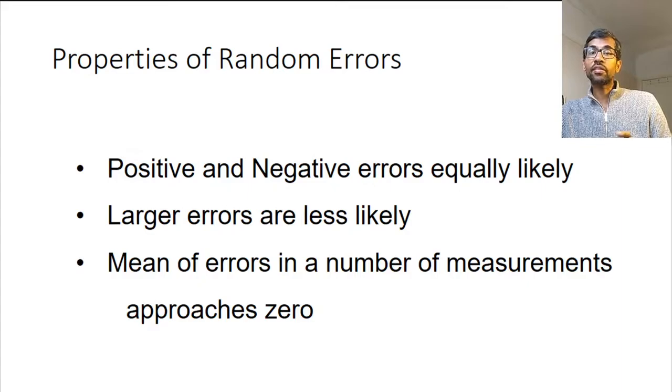Another way to figure out systematic error would be to get a validated instrument from somewhere, an instrument that has much less errors or that is more standard, and measure the output of your sensor or your instrument compared to that standard instrument. That could also reveal systematic errors. In general, systematic errors are much more difficult to figure out than random errors.